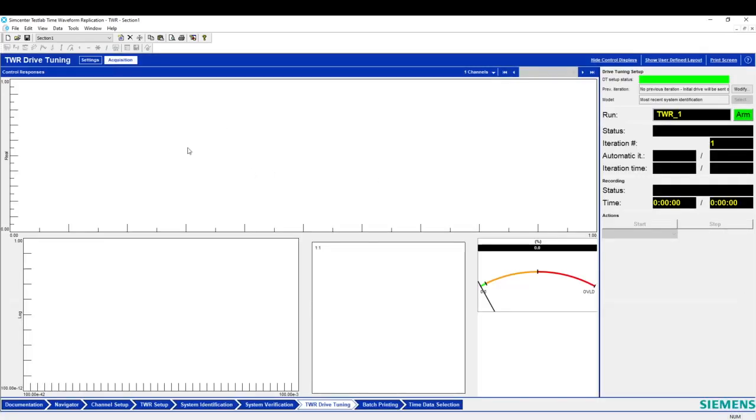Here we have different displays for different plot types. Before running the control test, I want to explain them to you. Here in the first plot, you will see the sliding time history of the measured and the reference signals, so in time domain. In the second one here, the PSD, so in frequency domain. This one instead plots the measured signal along the X and the reference one along the Y in a one-to-one scale. It means that if you see a straight line along the bisector of this graph, you are reaching the convergence, and the control is good.